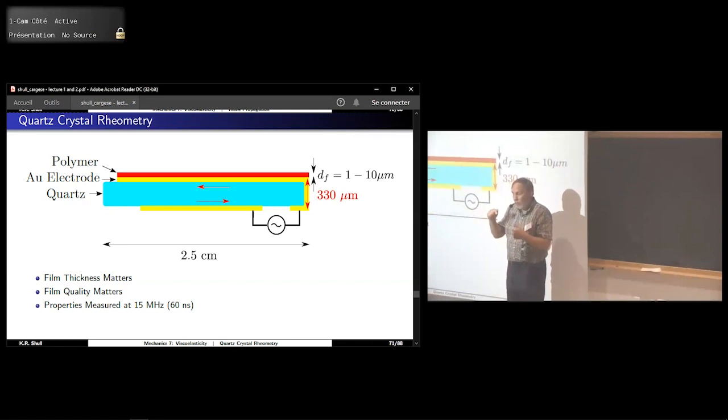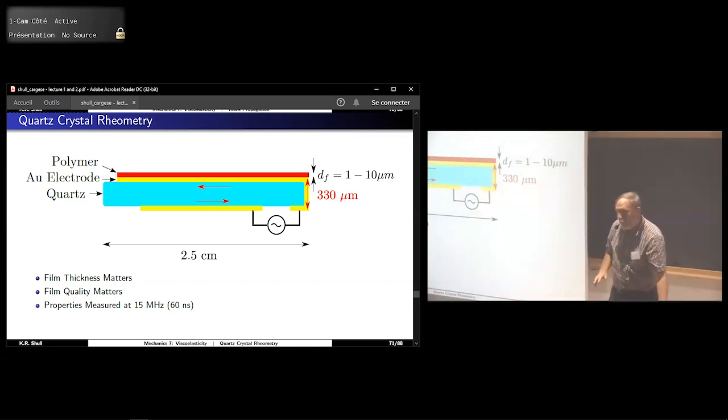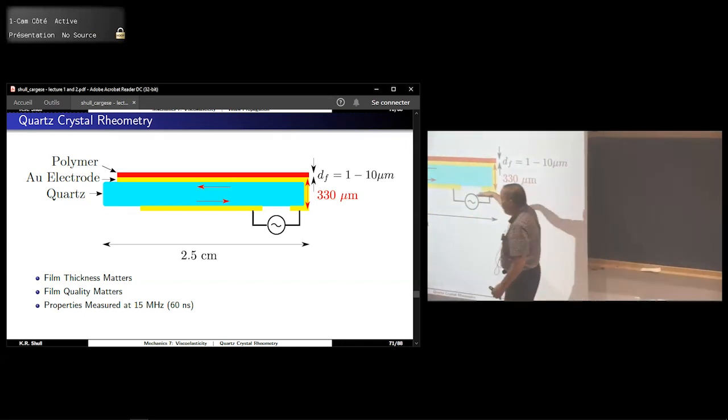So that means if you put an electric field in one direction, you're going to develop strains. And if you cut it in the right direction, if I put an electric field through this way, it actually moves this way. And it's very little motion perpendicular. It's all just doing this. So it's just the magic of the quartz itself that this produces a shear displacement.